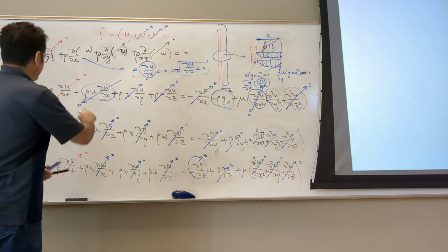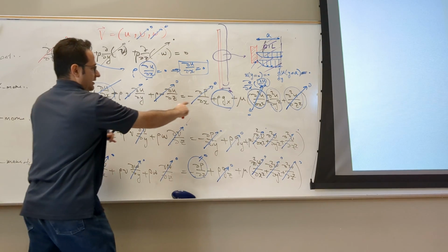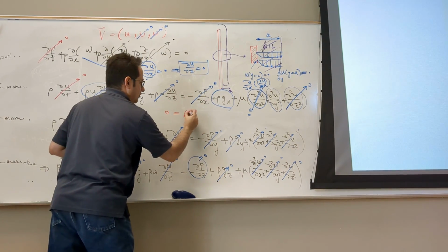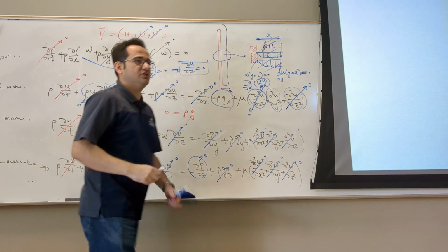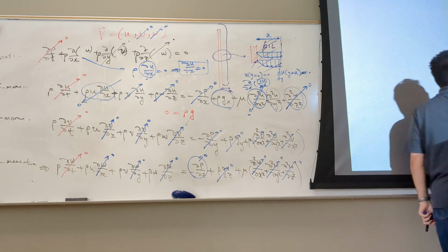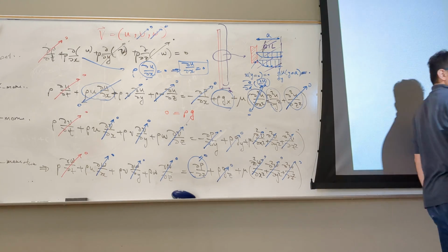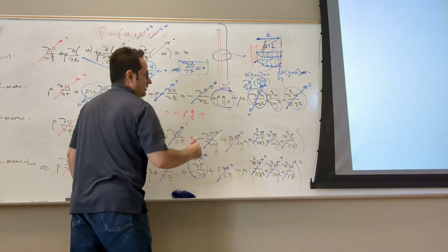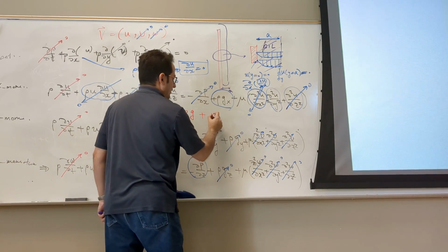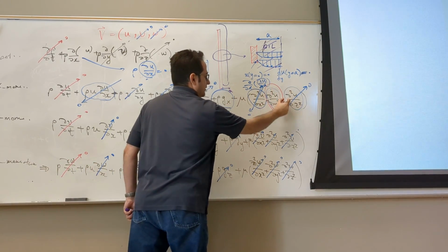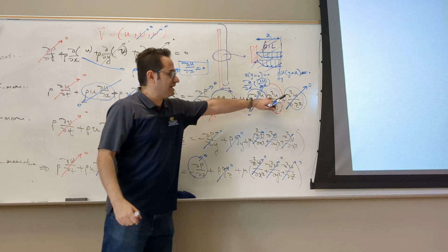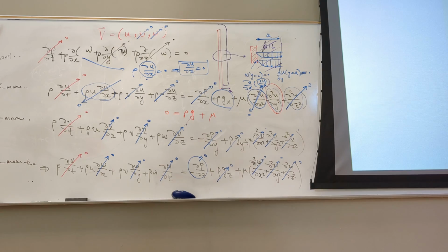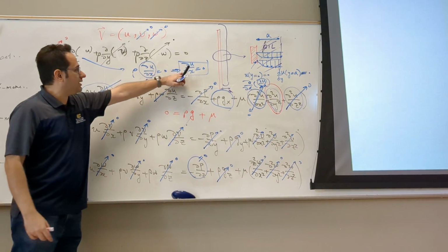So the final equation that is not 0, I want to write it here. These are all 0, right? 0 is equal to, this is non-zero, rho g. And what's the gravity in the x? Just g, right? 9.81. Plus mu times, you see, the only non-zero one. This is the one that you cannot make any assessment on. You cannot say it's 0. This one you could, you get it from continuity.